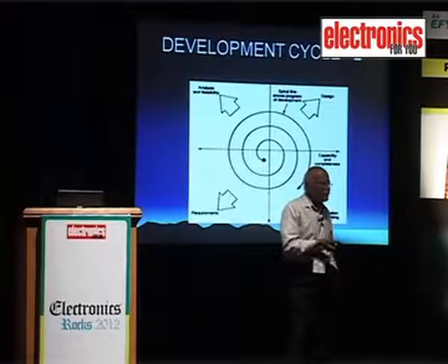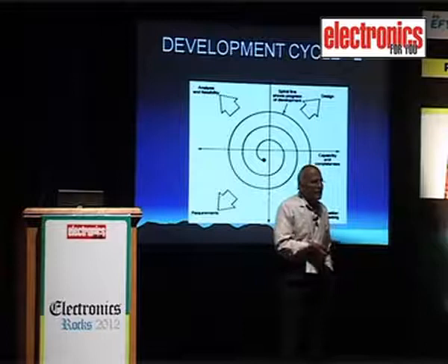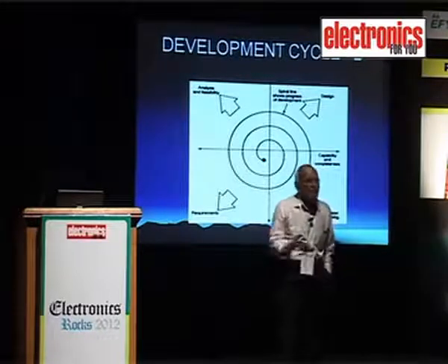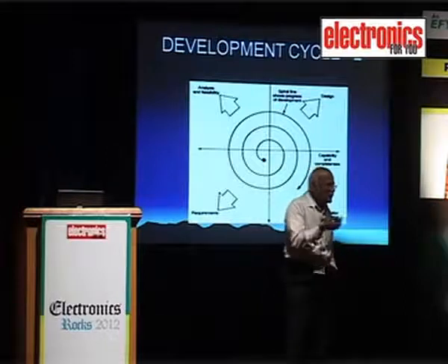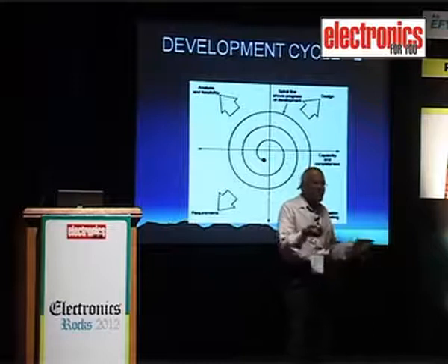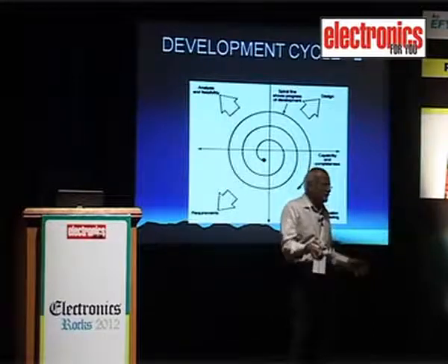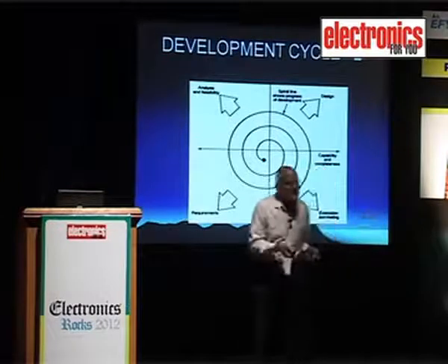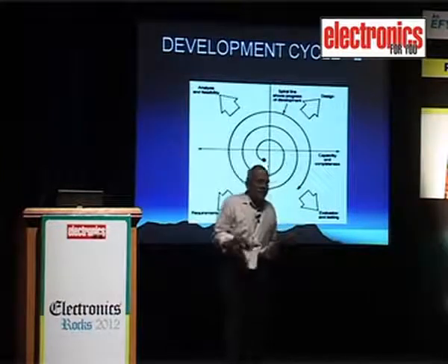Because suddenly after the Fukushima accident in Japan, they say that the accident which happened in Japan was because of loss of cooling. That is, the cooling system did not work because of the batteries. I mean, there is no water for the diesel generators to start on. The diesel generators failed, hence the equipment could not be cooled, so the reactor melted, and so many things happened there.